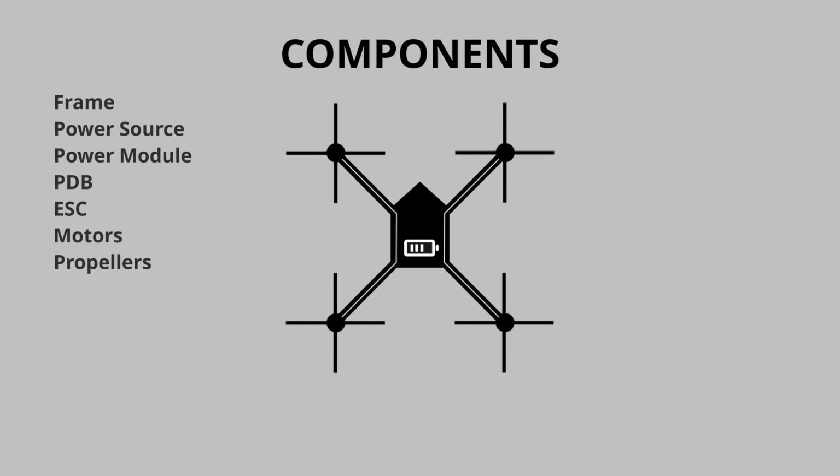However, this drone is not controlled in any way, and it would fly in a very unstable manner. You can power it up, set the thrust to half speed, and the drone would take off and it would crash. What the drone needs is a flight controller. A flight controller is a small computer which takes input from the IMU, Inertial Measurement Unit, which is a component which measures acceleration and angular velocity, telling the flight controller if the drone is moving, accelerating, whether it's tilted in any direction.